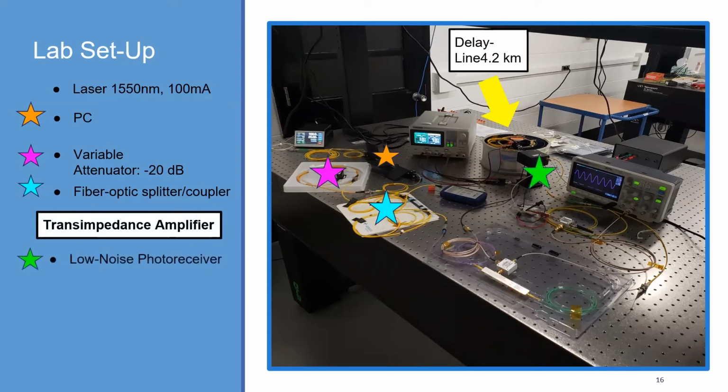Next, and this part proved to be very, very important, was the low noise photoreceiver with a transimpedance amplifier inside of it. This is again referring back to the previous diagram, where you take some optical power and convert it to an electrical signal. In this case, the responsivity S was about 40,000 volts per watt. So pretty powerful and very helpful in maintaining the linearity between the optical power to electrical signal conversion.